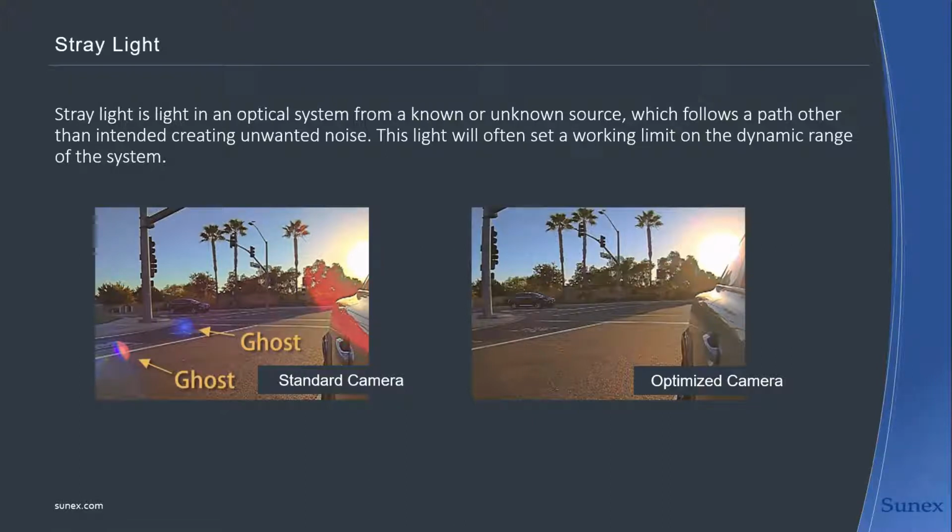Yeah, you're right. Several years ago, five years ago, nobody really talked too much about dynamic range in terms of sensors or lenses. Sensors at the time were 40 or 60 dB, and most of the lenses on the market, if they were decent lenses, were completely fine with that. But as the sensor dynamic range started increasing to 80, 100, 120, with those old lenses, suddenly you started seeing stray light artifacts and ghosts, exactly like what we're showing here on the left. They were always there. They just weren't detectable before with the older generation of sensors.